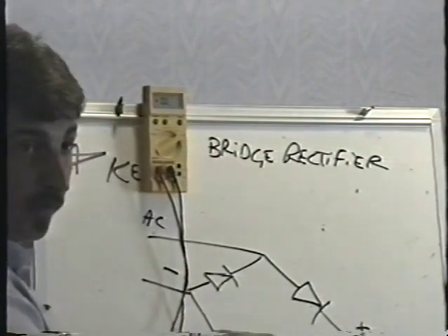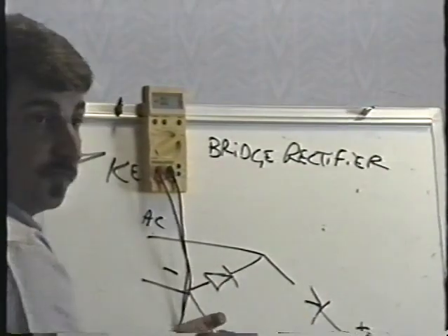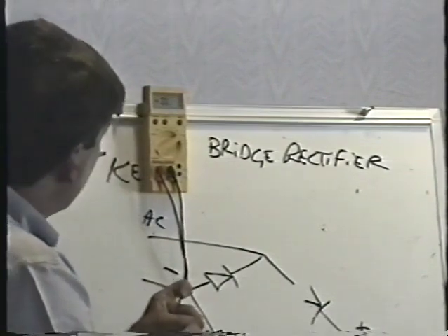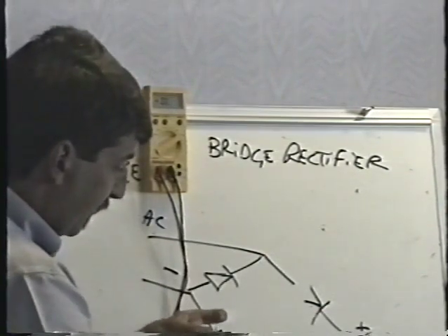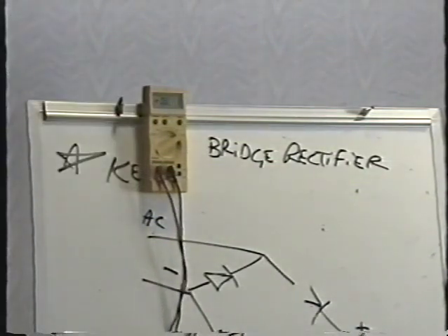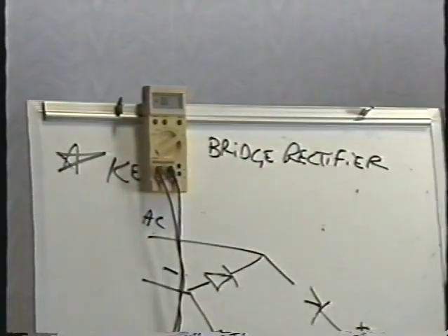One of these diodes is open. I'm getting an open reading both ways. The diode's open, which is pretty unusual. Usually they short circuit. That's interesting. I wonder where this one came from. So in this one, one of the diodes is open. That's pretty weird. But it certainly didn't pass the test. There's no question about that.